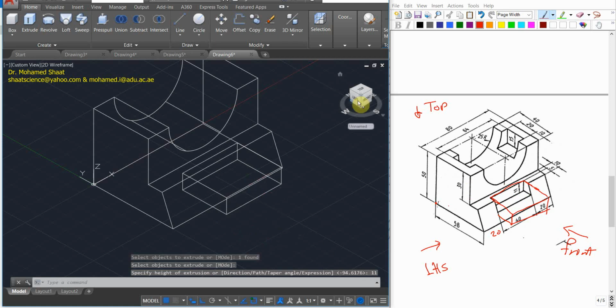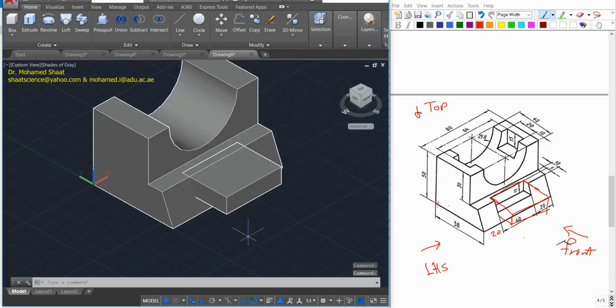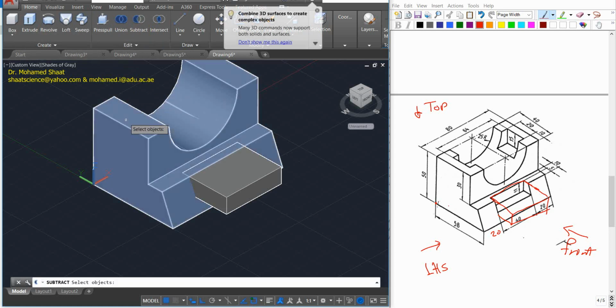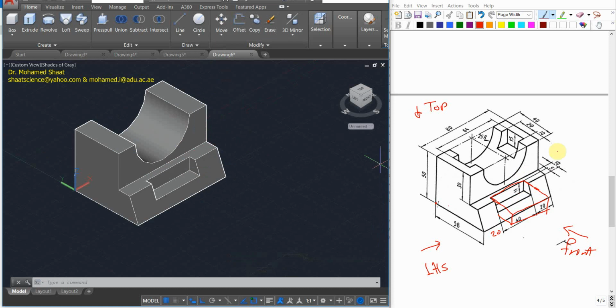So we end up with something that is already intersecting with the shape in the opening that we need to form. Okay, so these two objects, this one and this one, both are intersecting. So we're gonna use subtract from this object and press enter, that object and press enter. We're gonna end up with the opening automatically formed. Make sense? Do the same for the other one.